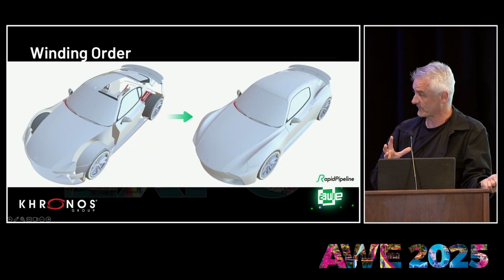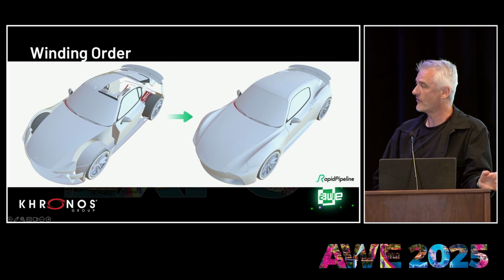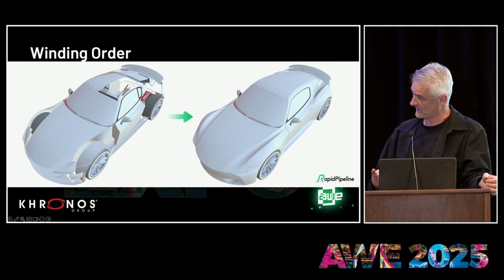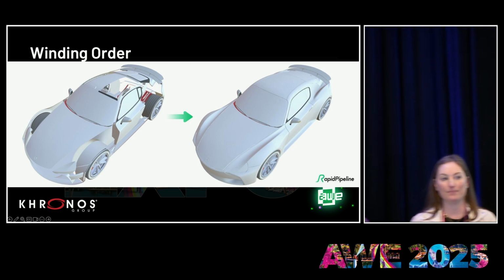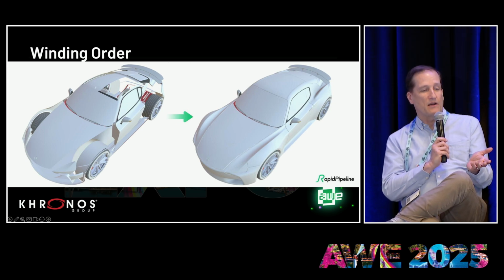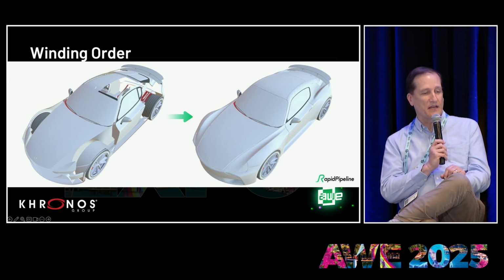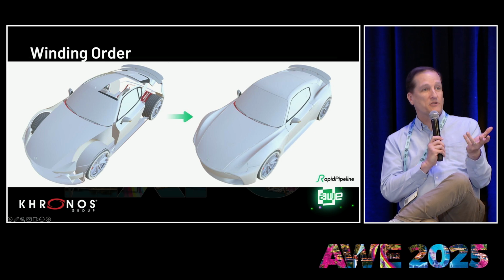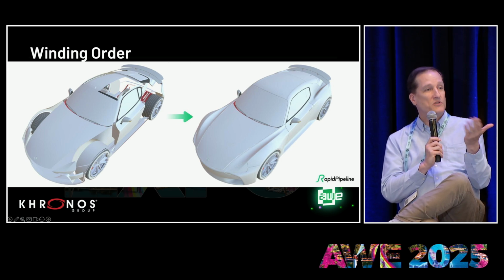That's a problem we've often suffered with a lot, right? Where we'll get a boat, say, half of it is facing a different way to the other half, and that can be a real problem. Yeah, so like the car on the left there, that's been tessellated, turned into triangles from the parametric data. But the parametric data doesn't really care about which way it's facing. You just render both sides at the same time. You render everything two-sided, and you don't see that problem.